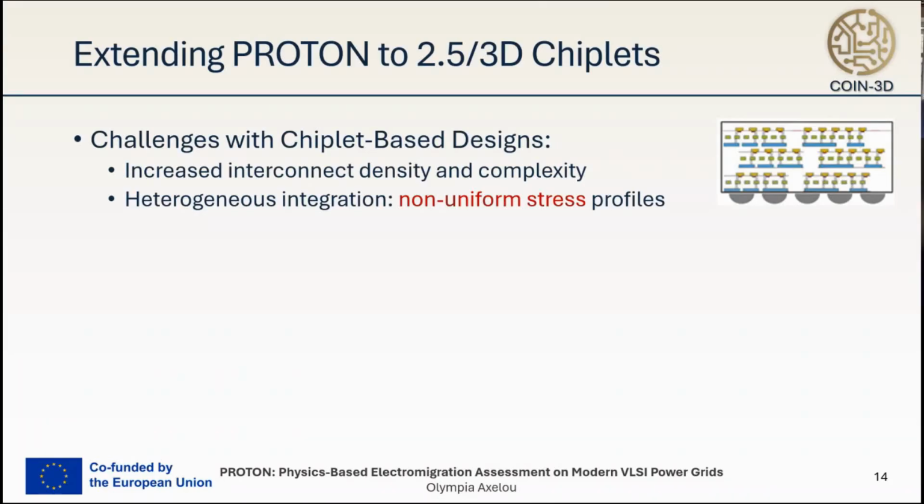And now, in order to conclude my presentation, let us take a step forward and think about chiplet-based designs. Now, chiplets bring unique challenges to electromigration analysis. The increased interconnect density and complexity can significantly impact reliability. And when introducing heterogeneous integration, we are faced with non-uniform stress profiles that are tough to predict. These issues are amplified for vertical interconnects like TSVs and microbumps that create stress hotspots.